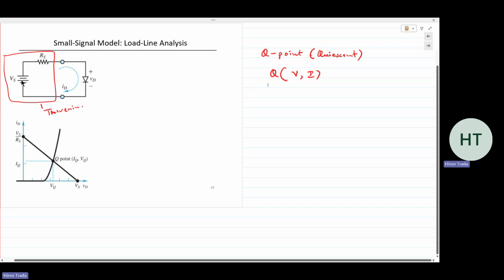We determined the biasing points of the diode, right? We set the input voltage, and depending on the input voltage, the diode voltage and the diode current change. As long as the input voltage is the same, diode voltage and diode current remain the same. So the circuit is now lying in wait, prepared to accept AC input.